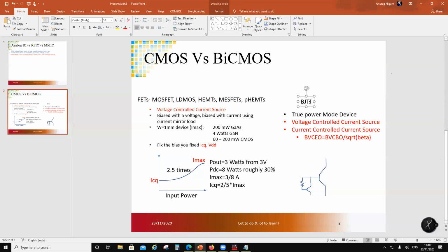And over here you have got HBTs. And what are HBTs? There are different flavors. SHBT, or single heterojunction HBT, where the base emitter junction is a heterojunction. Or it can be a DHBT, where both junctions are heterojunction. The collector base as well as emitter base junction are heterojunction. Now, what are the advantages? Actually, what you are trying to do here with heterojunction is tailoring beta. The base emitter junction is forward biased. The base collector junction is reverse biased, right?